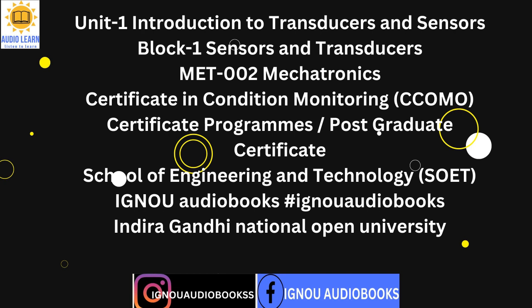1.7 Smart sensors. The next stage of sensor development is smart sensors, defined by the IEEE as a device with built-in intelligence, whether apparent to the user or not. These sensors are equipped with dedicated microcomputers for sensor-specific methods of signal processing. These sensors are also called intelligent sensors. The motivation behind the development of smart sensors is: A. Compensation for the non-ideal behavior of the sensors, and B. Provision for communication of the processed data with the host system.